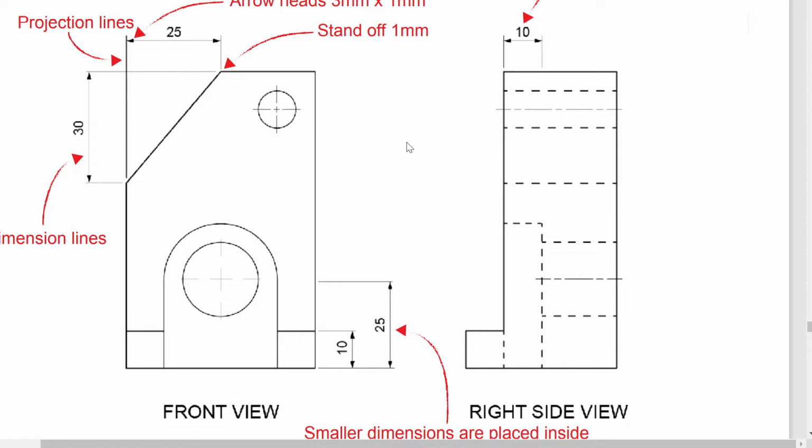Okay, so we draw the outside of the object with a thick dark line. Then we've got these holes that are going through the object, right? We have some things that are cutting through the object. I would have thought maybe that this was sticking out until I look at the drawing and see, no, this doorway, this arch shape, is actually pushed in. It's like a spot facing. But then these things here are like a step that is coming out of the drawing, right? So they're a step that's coming out, but this here is not a hollow, it's just thinner at this location. Then we have a hole coming all the way through.